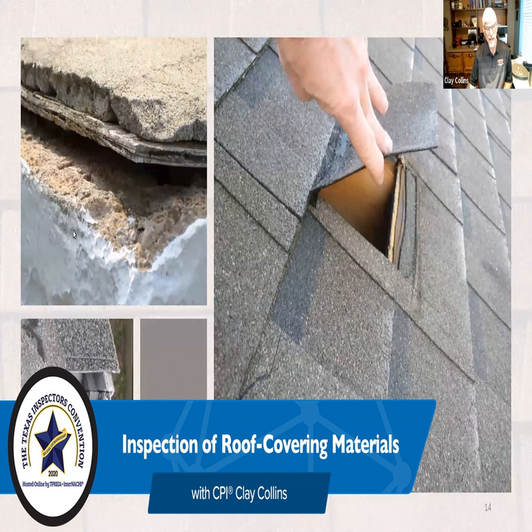You're required to report evidence of previous repairs to the roof covering, the flashing details, skylights, and other roof penetrations. There's no distinction made between the type of repair, the quality of repair, or the extent of repairs. You just at this point report repairs. We'll talk in a second about the quality of repair, but all that you're doing here is saying this roof has had repairs, and that might explain some of what you see in the attic, or what you see in the ceiling covers.